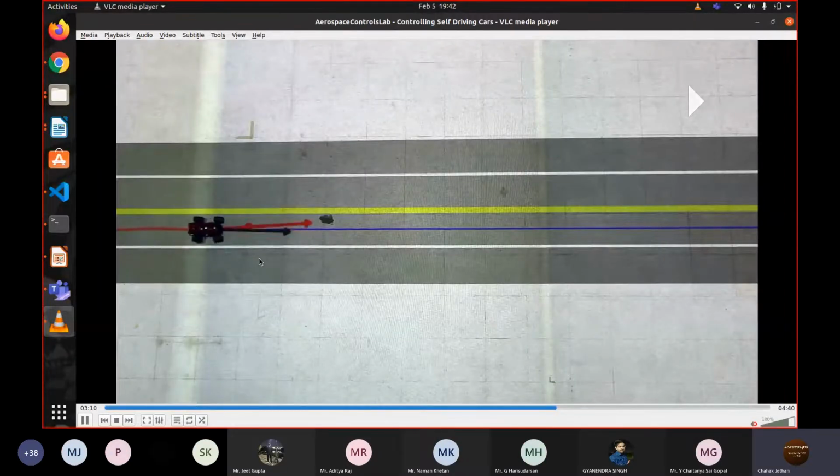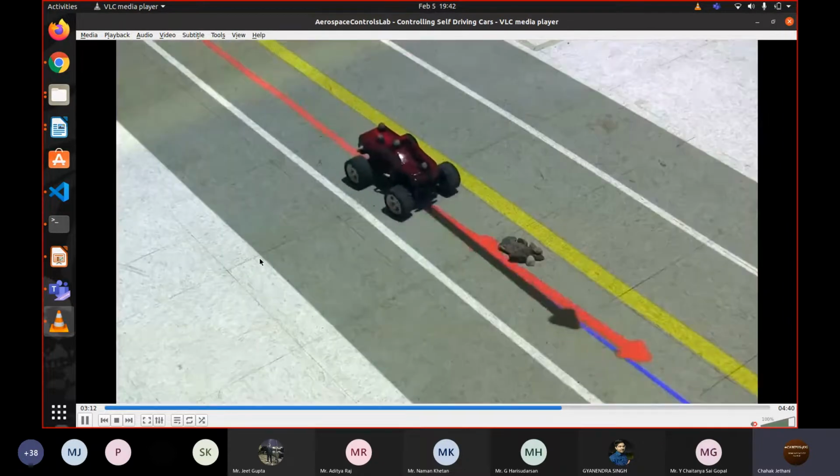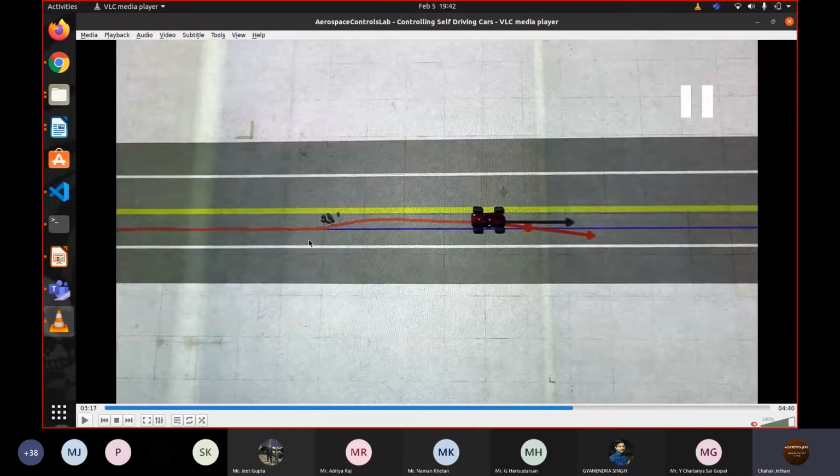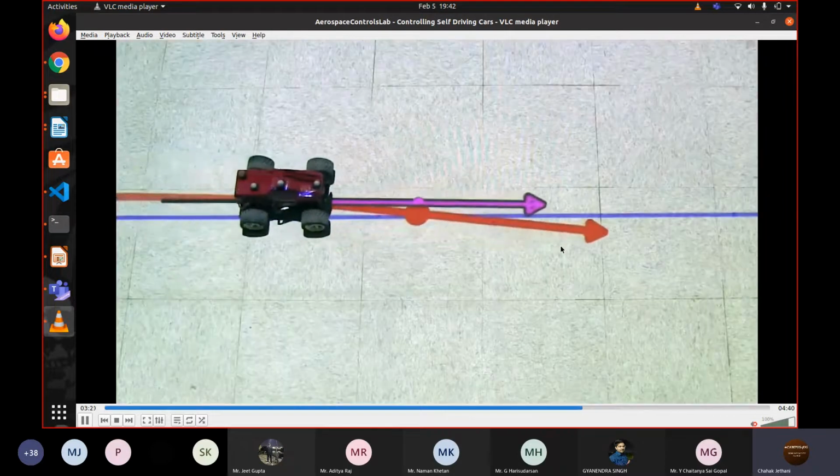Okay, so now through this visual, I will explain you what the integration term is for. Okay, so as you can see, because of the pebbles, the car is displaced only a little, and because of little displacement, the proportional gain and the derivative gain, both of them are not enough to orient the car. Okay, so therefore we have to also introduce another term, which is integral term.